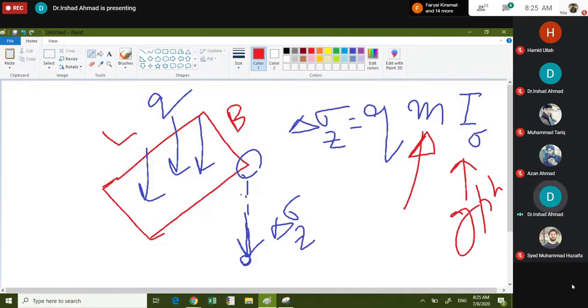If you want to find the stress under the center of footing, this equation is not directly applicable. For this to be applicable, you need to divide the rectangle into 4 sub-rectangles and find the stress for this rectangle.